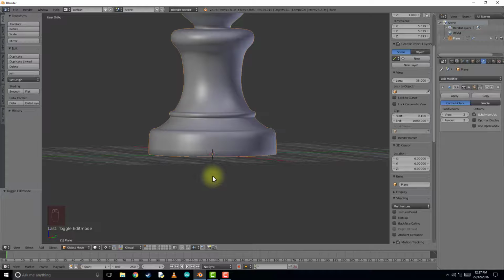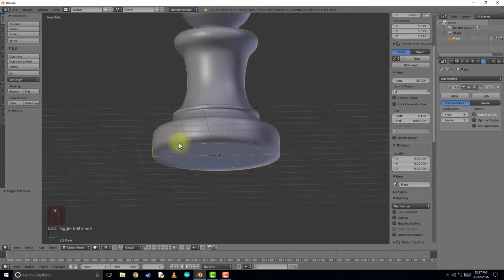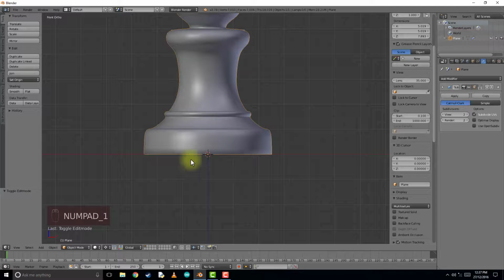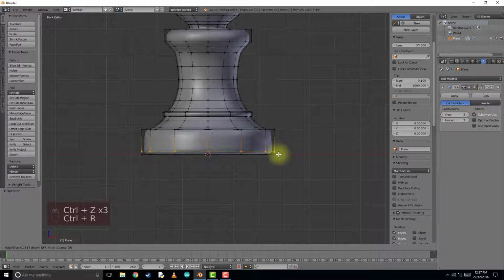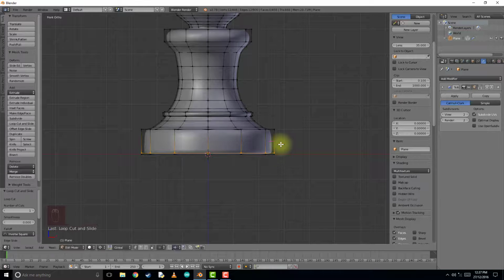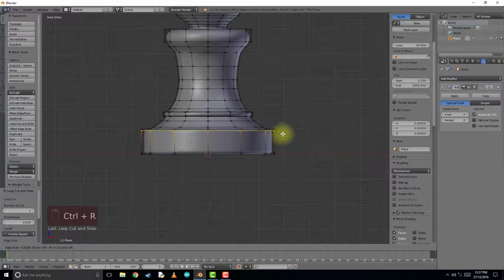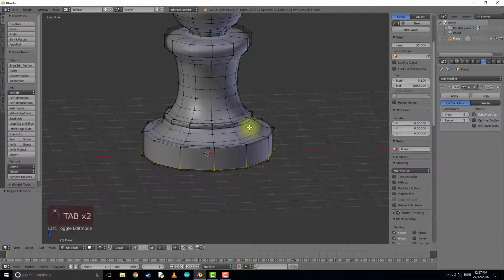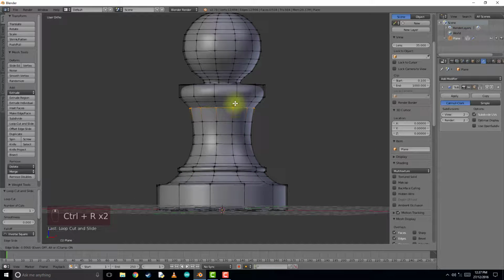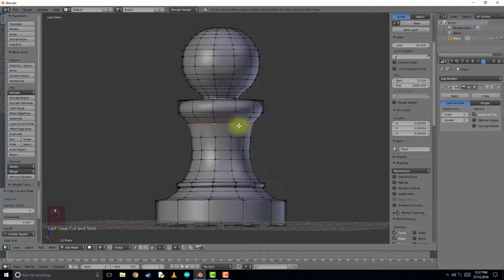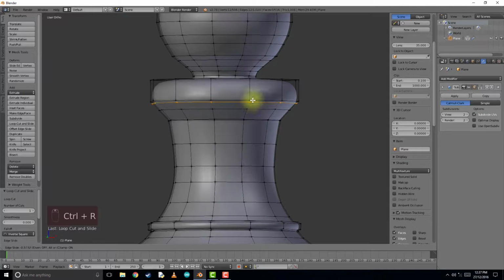The other way to do this, when rendering is more appropriate, is by adding another ring loop by pushing Ctrl R, then left clicking to confirm, and then we can transform it closer to the edge, and we are sharpening these edges. If you do want to 3D print this object, try not to put them directly on top of each other. This could cause ugliness when exporting the STL file. Just bring it close.